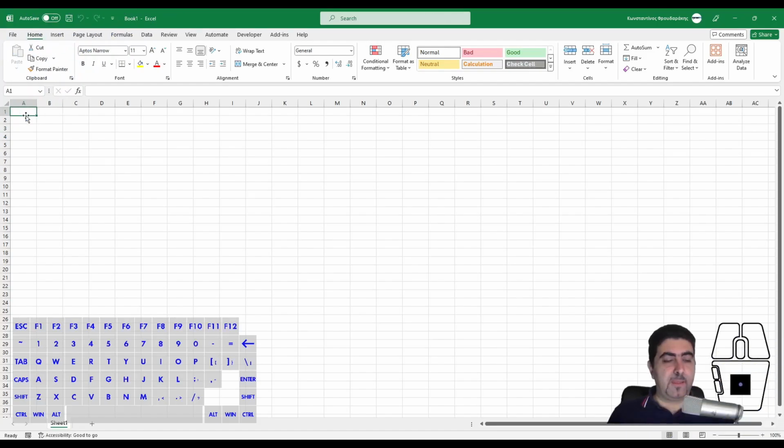Those data, those parameters you create in Excel come in as Alibre parameters, and you can assign them to various parts of your design, which will then be used to adapt your design, right? Now, the way this works is you create columns whose names will drive the Alibre parameter when it is imported.